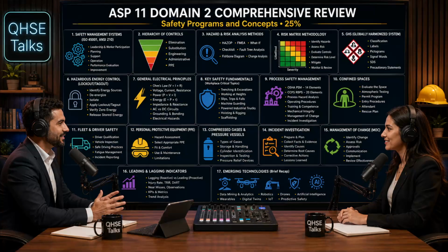Okay, I want to take a breath here and just zoom out for a second. We have unpacked a mountain of discrete, highly technical topics today. ANSI standards, LOTO, risk matrices, crane physics, leading indicators. But the exam and real life require us to see how all these pieces snap together into one cohesive safety management system. I'm really glad you brought this up. The exam doesn't just test definitions, it tests synthesis. Let's trace the complete life cycle of a hazard through everything we've just discussed to see the ecosystem at work.